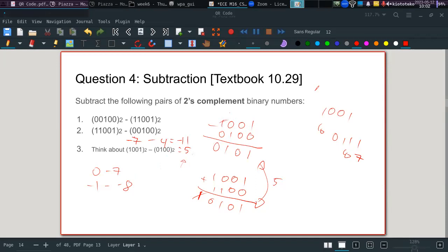But if it's two's complement, then the most significant bit is actually on this side, right? So how does borrowing work? No. When you perform subtraction, you don't care about whether it's two's complement. You just perform the subtraction. Only when you want to perform addition, then you get the two's complement of the one you're subtracting, like the one at the bottom, no? But if it's normal subtraction, you just subtract and get the value, no? Any other question?